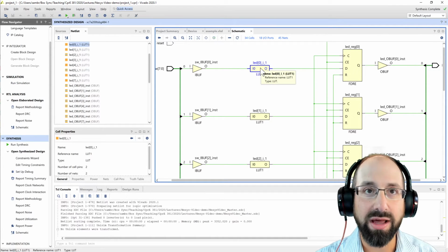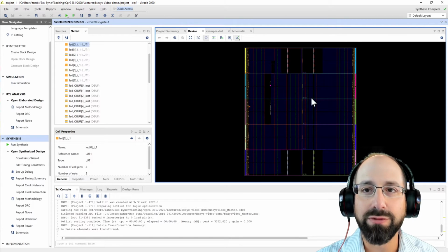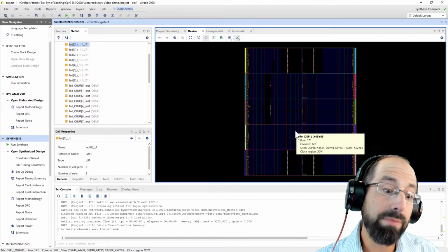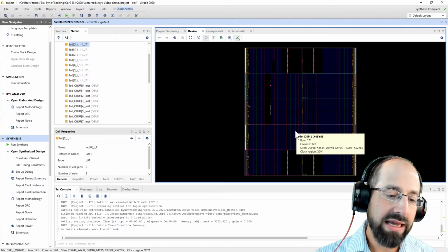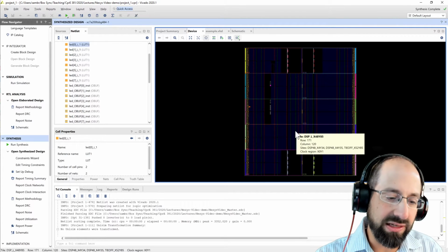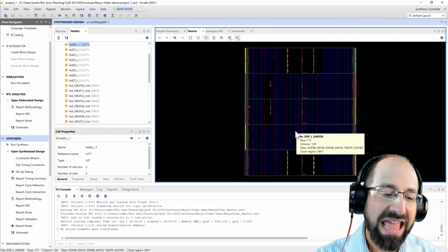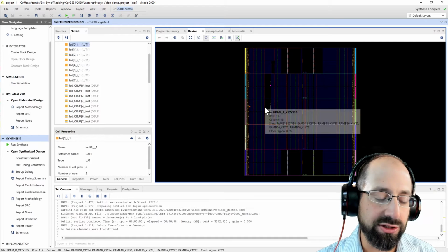And there's a lot of them on the chip. Depending on the chip, there are tens to hundreds of thousands of those lookup tables. Between them, you have relatively complex functionality you want to implement. It all gets broken down into these truth tables, and lots of algorithms are being applied to that process. And then they're all getting mapped to what's available on that particular device.